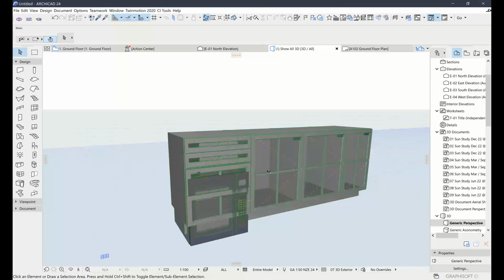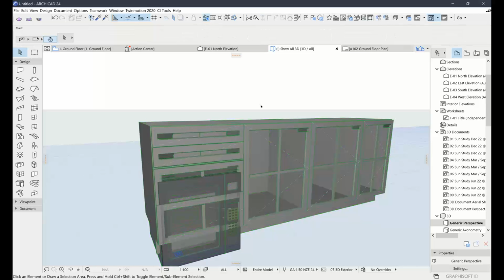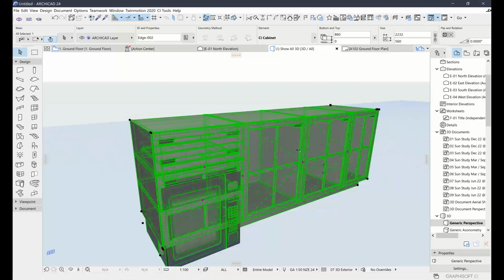So at the moment, with the way that the tool works, to add those, in floor plan view you can stretch it and it will add vertical module separators, but to do the horizontal ones, you need to do that in either your section elevation or 3D views. We are working on some updates to the cabinets tool, which will be coming at some point in the future.